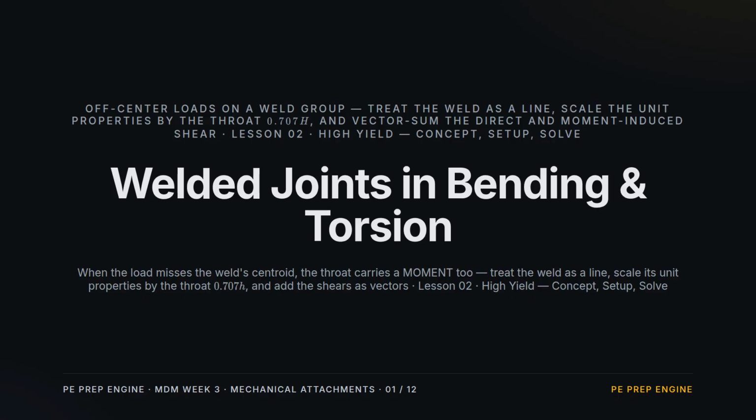Treat the weld group as a thin line, look up its unit properties, scale them by the throat, and then add the direct shear and the moment shear as vectors at the worst point. Get those two habits right, and the bracket problems on this exam fall out.